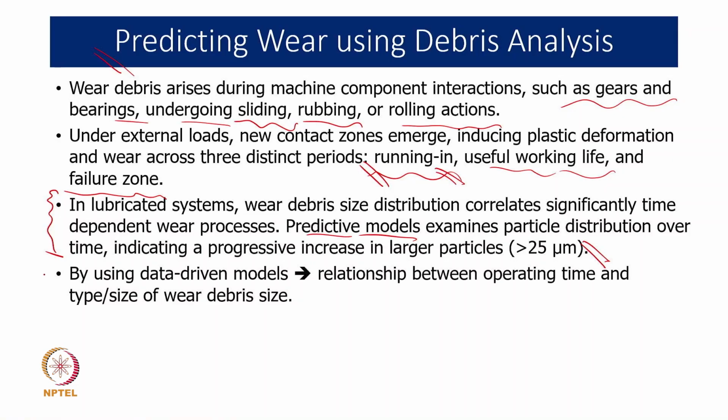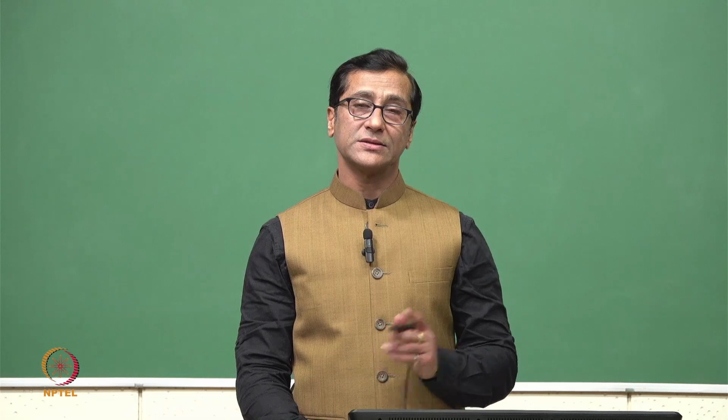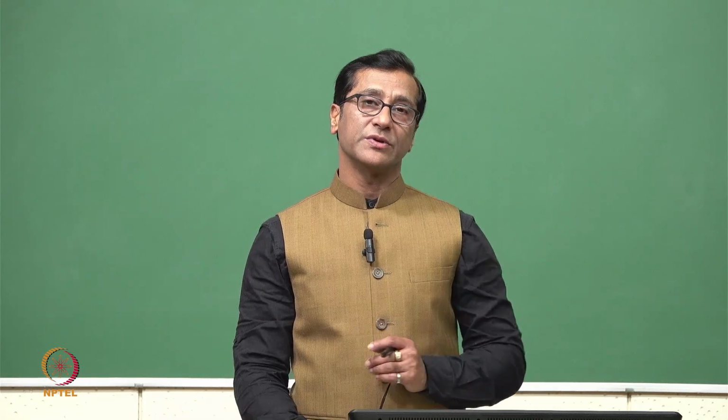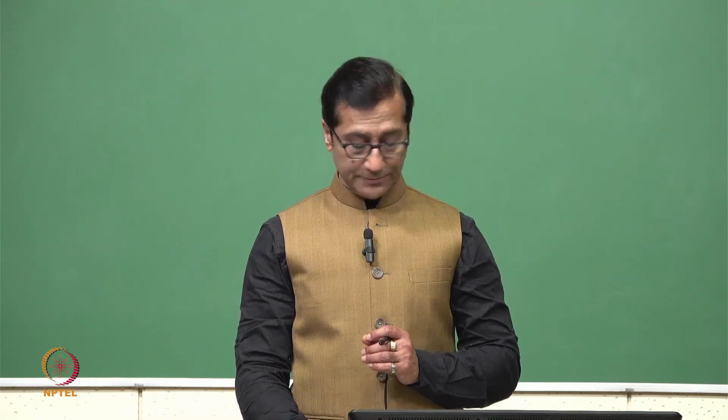And moreover, when we are going ahead with data-driven models, we need to have some sort of relation between operating time, size, and type of the wear particles. If with operating time the number of particles is continuously increasing, which many times we call trend analysis, then naturally the wear is increasing significantly, and we need to take appropriate care.